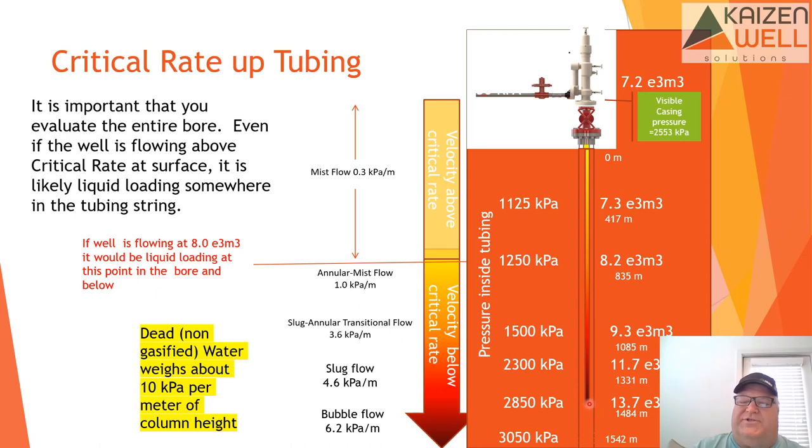Your end of tubing pressure is going to be much lower, and this is basically why, as your well loads up, you can see the pressure go up because the column weight increases, forcing that formation pressure, or the area near the end of tubing, to start to build up. Eventually that column weight will overcome the pressure you have in your formation, or could, and then the well stops flowing. So that's there.